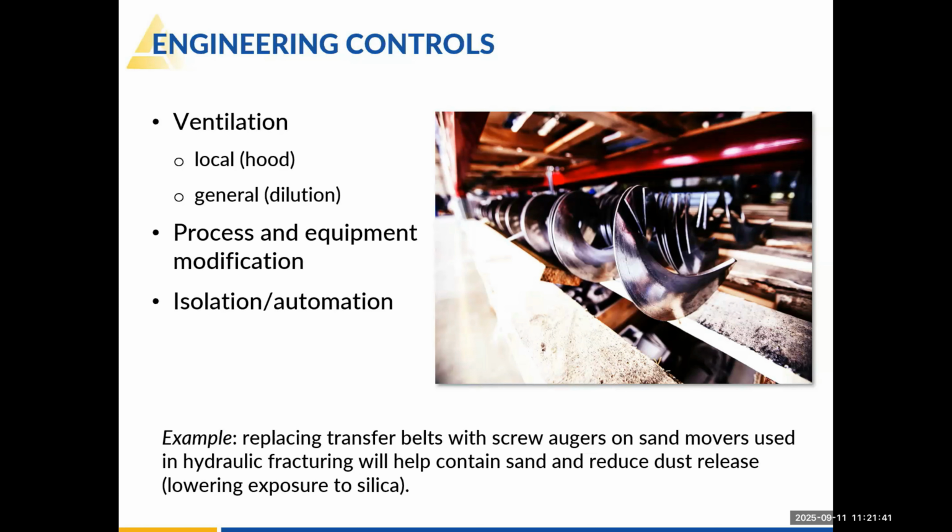And then isolating and automation. Isolation, I've got a client that was pretty crafty with, they had a noisy machine out on the floor. I believe it was an air compressor. It was creating a lot of noise. And what they did for an engineering control was they hung acoustic paneling, 4x8 sheets. I think they were 2 feet thick, and they hung them from guide wire from the ceiling and completely encapsulated that particular machine, greatly reducing the sound levels out on the floor.